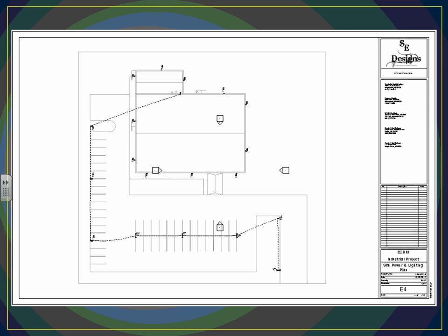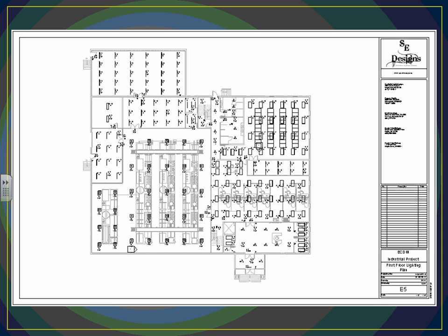Here's your building and parking lot, so we do all the design for the parking lot and what not. The building is made of 2 stories, and that's what we're going to be sizing for. The first story has an open manufacturing floor right here with bus duct coming from the top and feeding all these machines, owner equipment. The machines are coming in here at 2 different voltages, 208/120 and 480/277, to complicate things. So we're running 2 bus ducts.